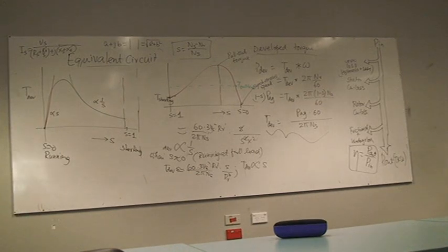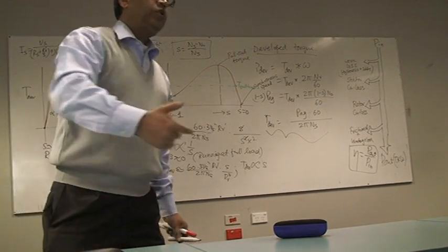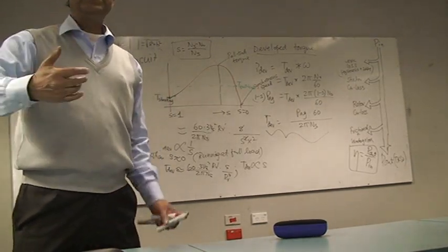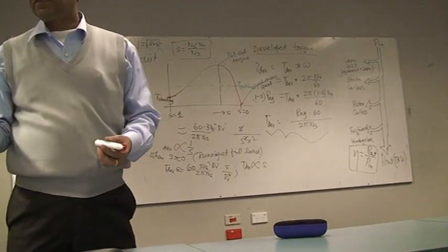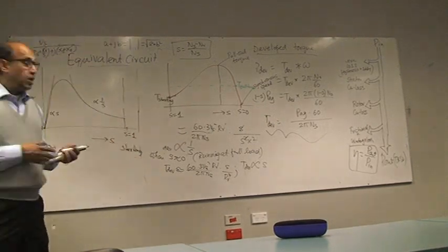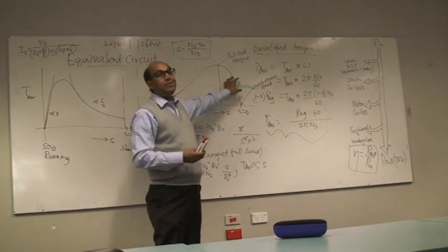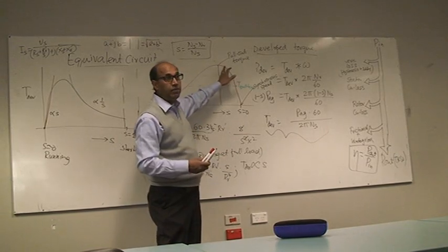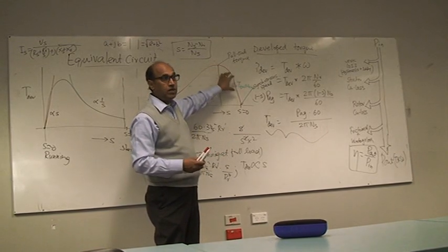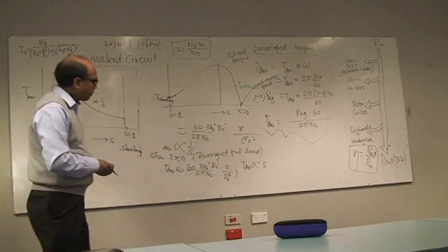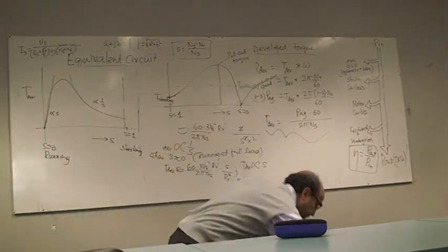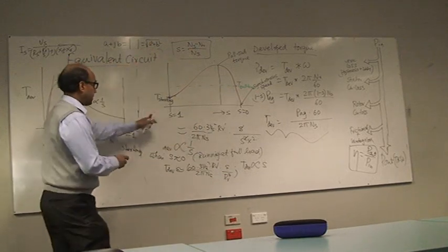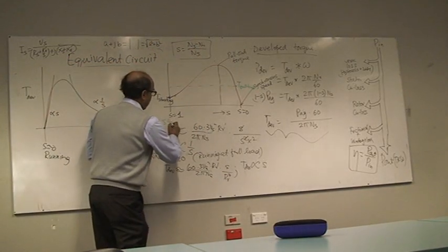But then you may say, why do I need to have such a big amount of pull-out torque? You need to accelerate. Also, you sometimes need overload capacity. You do not want your motor to fail when your torque slightly becomes higher than the full load torque. How much ratio depends, like 150 to 180% of the full load torque. S is decreasing from left to right here, because at starting S equal to 1. So that's your starting.